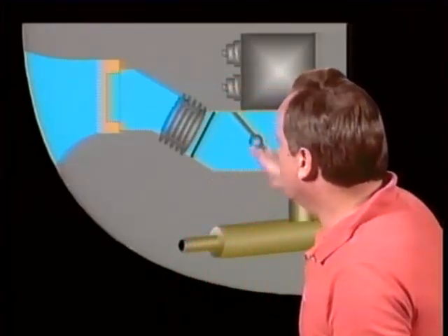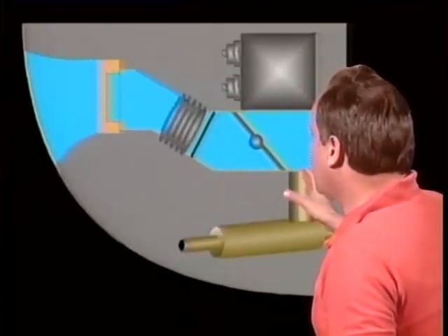So a factor in the failure of an engine to develop full power at takeoff could be due to improper adjustment of carburetor heat valve control linkage. In other words, some of the air going into the carburetor is hot air when you're trying to take off, and of course reduces the performance of the aircraft.